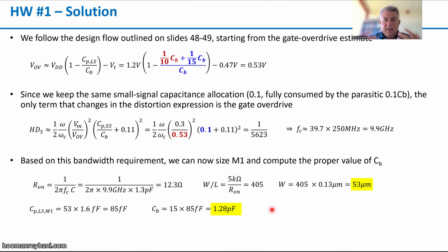So you see the outcome is somewhat logical. We have more parasitics on the top plate of the bootstrap cap. So we pay this with a larger bootstrap cap and a larger switch to get the same specifications in bandwidth and so on. That leads to the rejection of this additional parasitic.